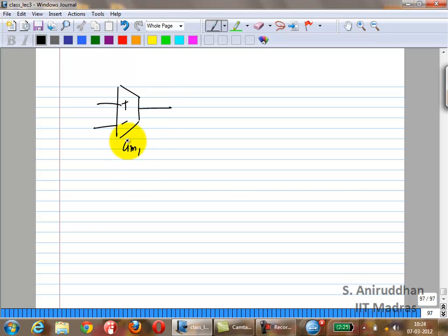Let's start off with this. The GM1 stage. What is it going to look like? Diff pair with resistive loads? Capacitive loads, not capacitive loads, but active loads or what? What do you want here? You definitely want differential to single-ended, right? So the most commonly used pair we have seen is the diff pair with active load. So we'll start off with that.